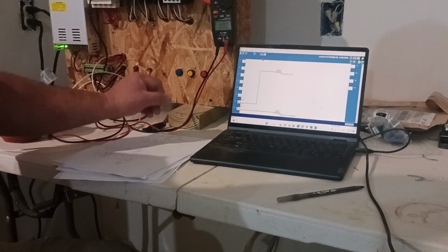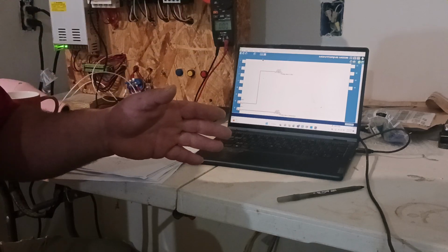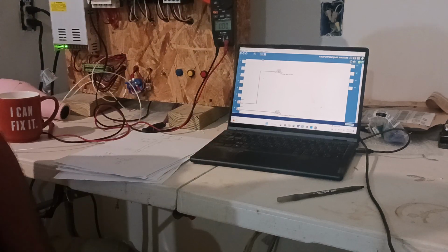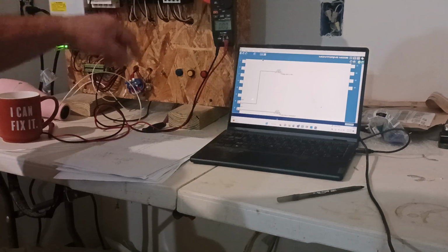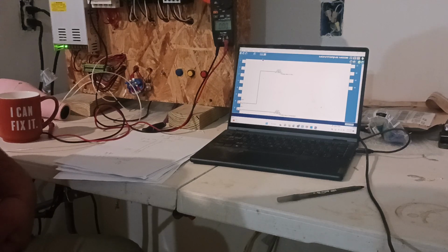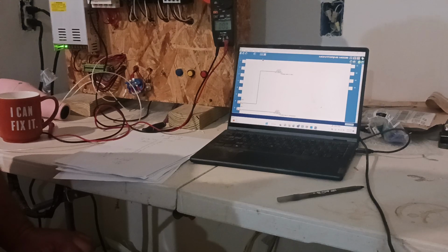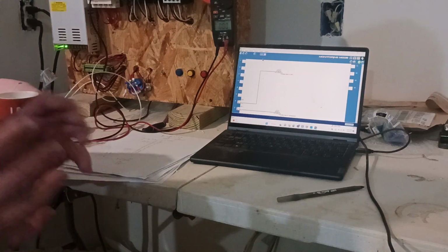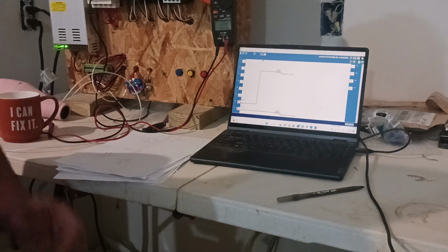was engaged, right? Or my photo sensors, when something's in front of it, it gives 24 volts. When things are removed from in front of it, it gives 0 volts. So, we've been talking a lot about discrete digital inputs and outputs, basically 0 or 24 volts. The 24 volts would operate things like the ice cube relays or the motor starter, which would do these lights and stuff like that. But now we're going to talk about something a little bit different, where you don't just get 0 or 24. In fact, you will get a signal on a range.